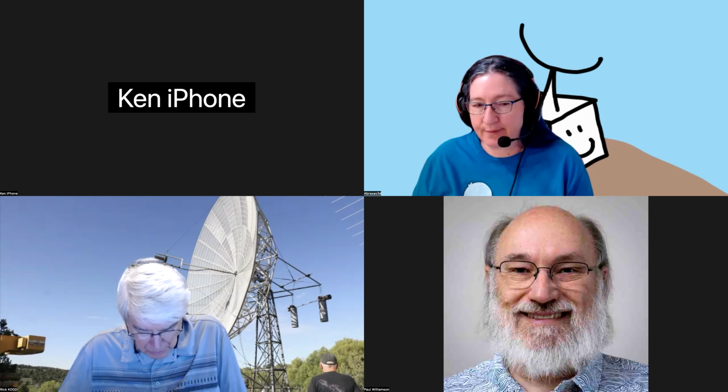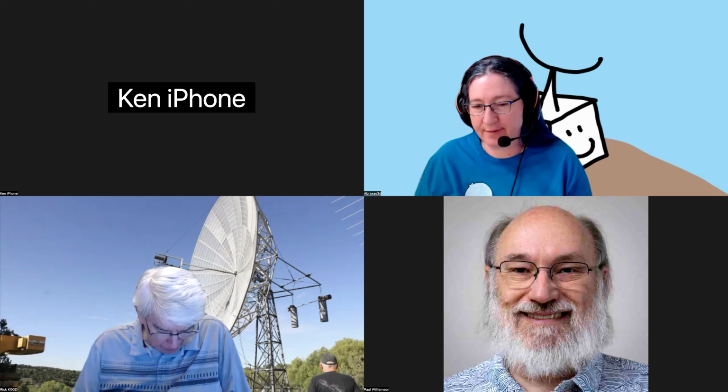That might be like the lane rates on the SERDES drivers. So I'll go see if that might be related, and go back and look at the lane configuration, see if that should work on all devices or maybe just certain devices. TES is supposed to screen for invalid combinations and invalid parameters, but something about what it spits out, when you compile that on target, doesn't like that.